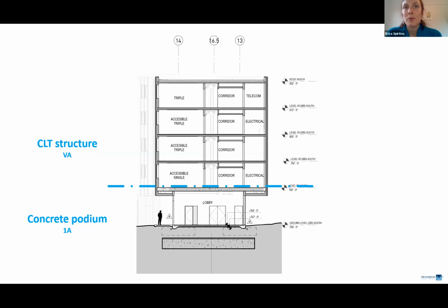So when we usually build type 5 structures, stick-built walls with I-joists, we're not modeling them necessarily. Maybe a contractor is using 3D modeling for coordination or clash detection, but certainly not for fabrication. And so the level of detail and the level of effort that's required in that 3D modeling process makes it a whole different ballgame, because we're trying to coordinate penetrations precise to the 16th of an inch through the CLT deck and making sure that there's no issue in the routing of mechanical, electrical, plumbing, fire sprinkler services through the walls, vertically and then horizontally across that deck.